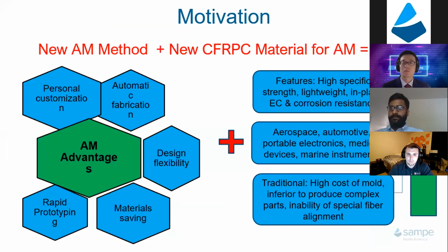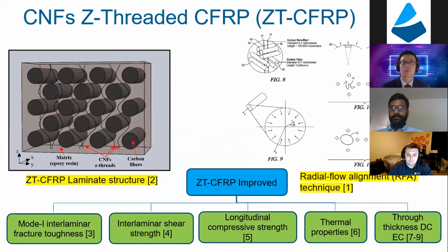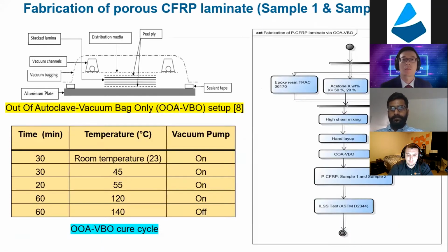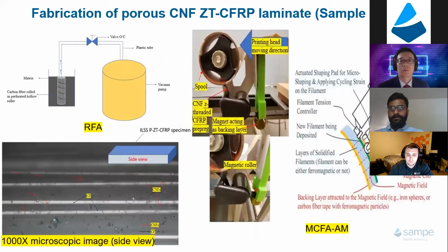And then now we add additive manufacturing by using the magnetic impaction. Then we need to change the resin. For additive manufacturing, we use a thermoset. The reason is we got it from Hexagon, and it cures in about 45 seconds once you turn on 140 degrees C.